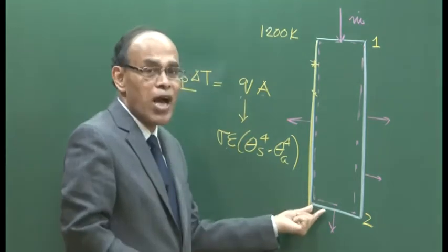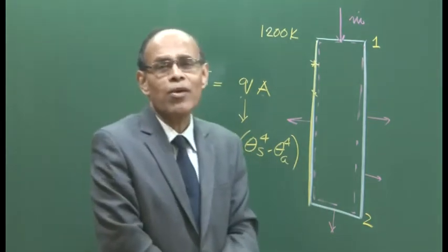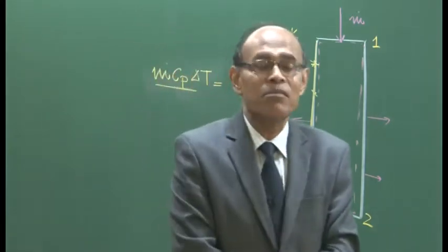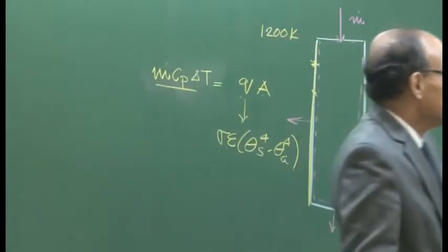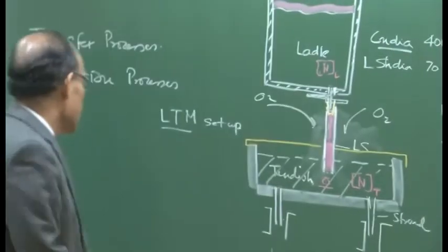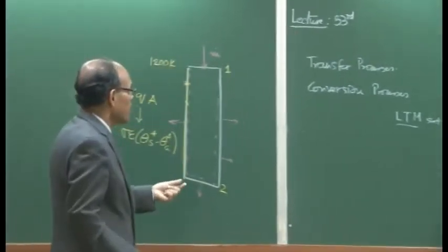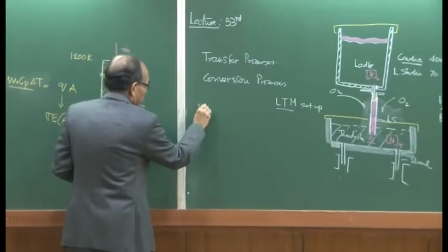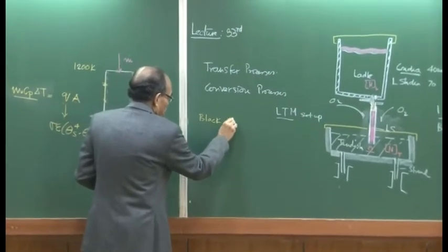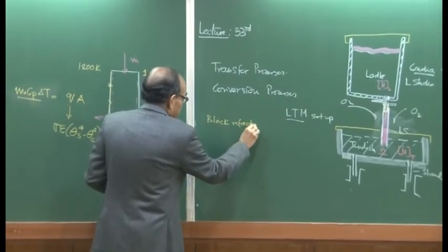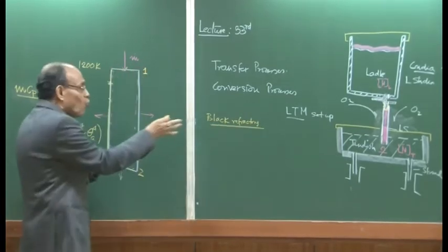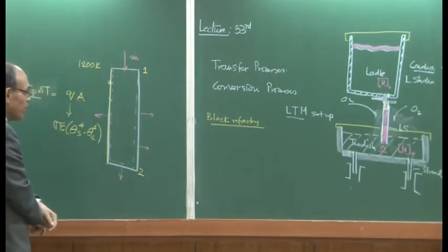We also have a lot of carbon in it. They look black, and that is why I think most likely in industry, ladle shrouds, then tundish furniture, nozzles, they are categorized as black refractories. Possibly they contain graphite to ensure that there is good flowability of molten steel over it, there is not much wettability.